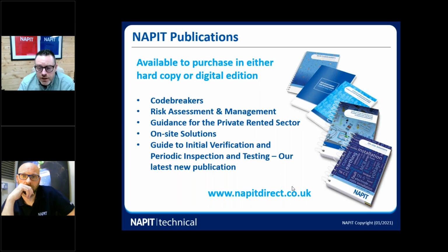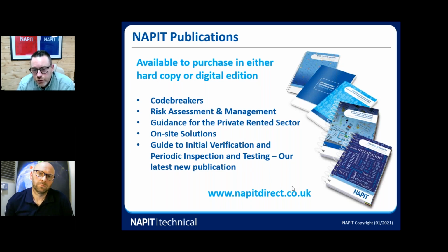It doesn't mean to say the installation has to meet the requirements of the 18th edition. It doesn't need to be upgraded. It just needs to be checked that it's safe for continued use based on the 18th edition regulations. And that's always the case when you have a change of regulations. You test at the current edition, not the previous editions, because those regulations are no longer applicable. You need to comply with the current edition.